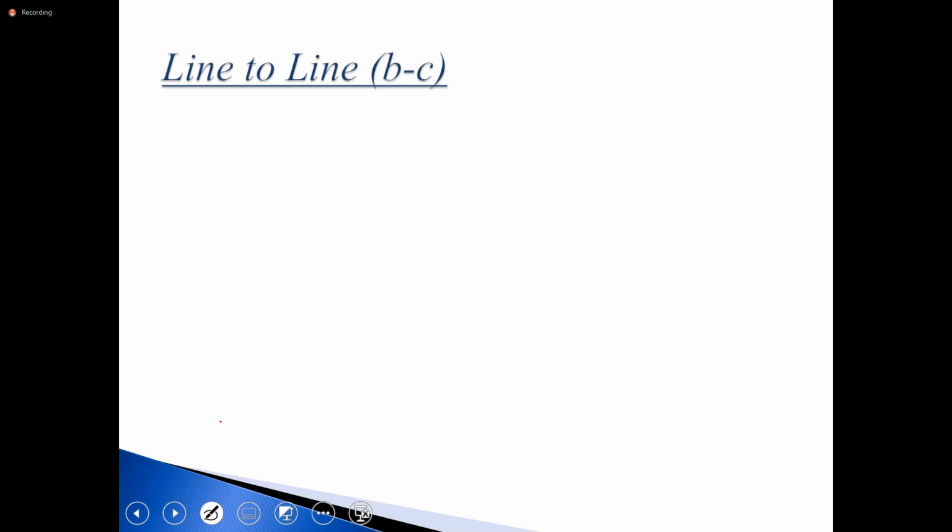I also need to make the note that what we're looking at here, these fault types, are what we refer to as unsymmetrical faults, where not all phases are impacted in the same way. Your symmetrical fault would be a three-phase fault, where all three phases are impacted simultaneously. So we are looking at unsymmetrical faults. Just a note.